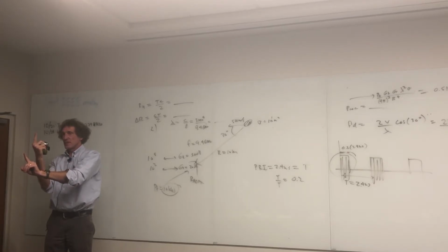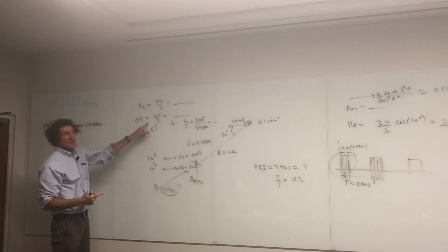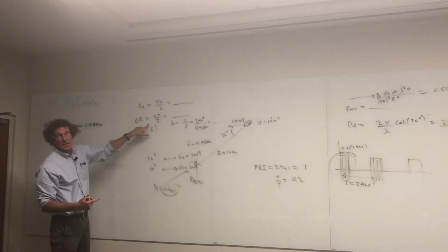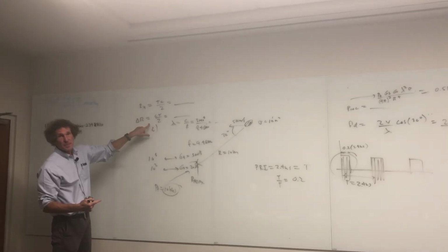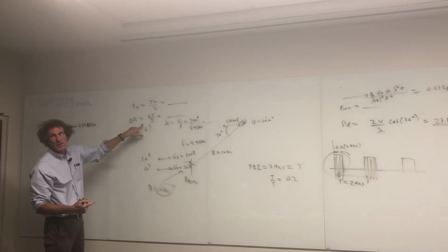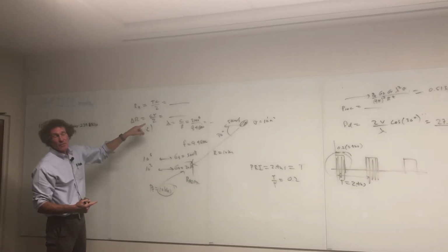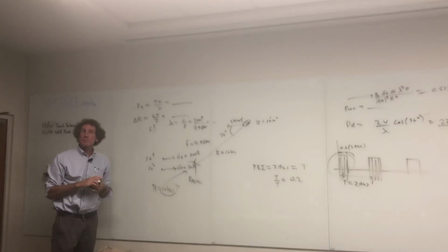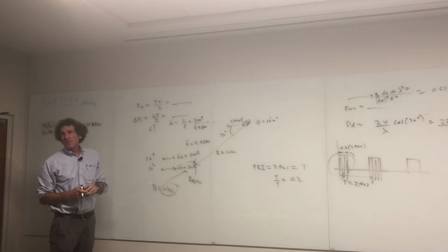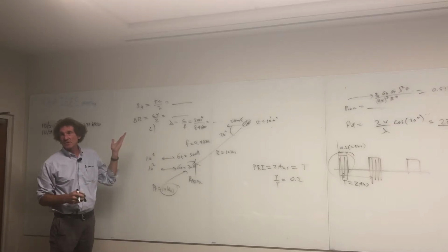This tells you the range, how far out you can see clearly, you might say. Anything out to that range, when it gives a return, is non-ambiguous. Usually the way they do this is by the time you get to the non-ambiguous range, anything reflected back from any targets you expect will be in the noise and you won't be able to see it anyway. That's the way they design these things. At least it's part of the design process. So that would be for that one. This would be the maximum unambiguous range and the range resolution.